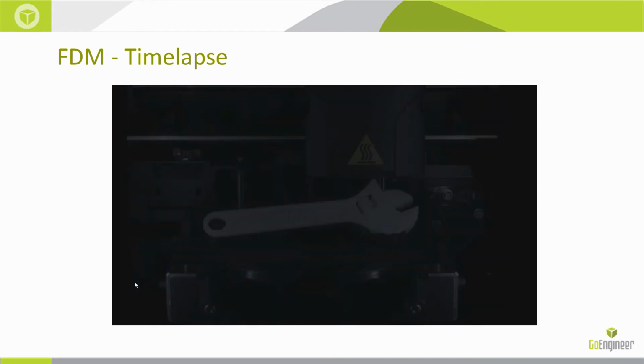The root beer color material is the support material. And that support material is there only to support where needed. So this allows us to print any geometry imaginable. We can print undercuts, we can print internal passageways, we can print entirely enclosed voids if we want.